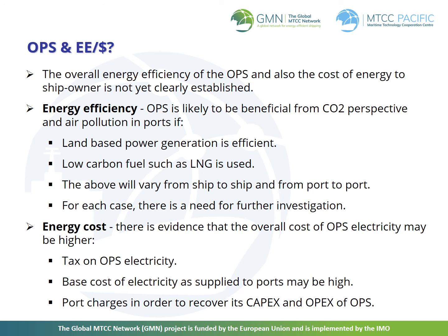Although both have been advocated by OPS enthusiasts as justification for OPS and reduction of a ship owner's energy costs, this topic is not certain and most likely will vary from case to case. The energy efficiency of OPS relative to shipboard generation needs to take into account all the various forms of energy transfer and transformation losses along the transfer route. In addition, the thermal efficiency of a land-based power plant versus shipboard systems needs to be taken into account.